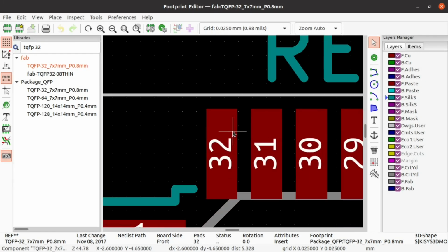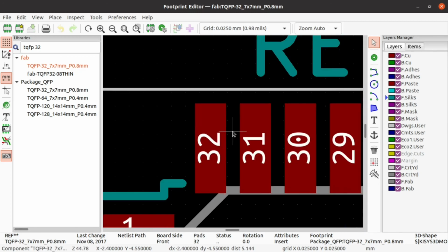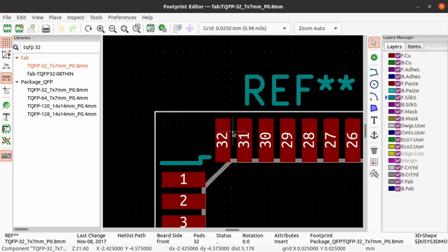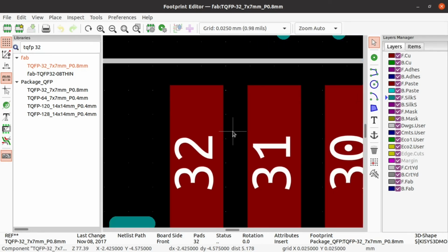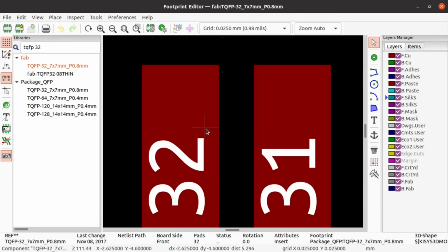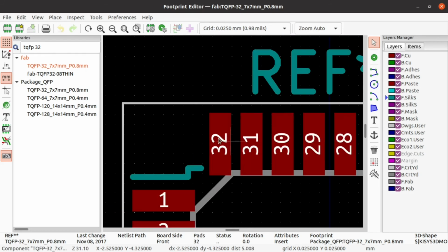One thing that is important to check is the spacing in between the pads. Because we are milling with limited size tools, usually it's 0.4 millimeters, but the smallest tool that we have at the lab is 0.3. So for these high resolution, smaller pitch components, we are using the 0.3.